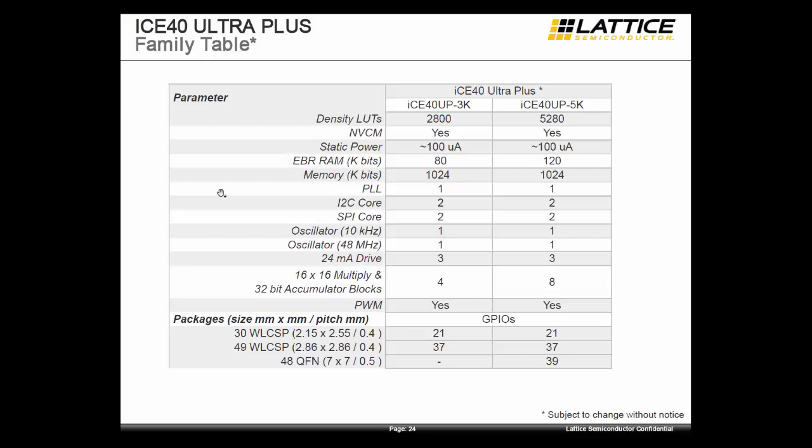The 48 QFN package is a 7 by 7 millimeter package with a pitch of 0.5 millimeters. And the QFN packages do contain all of the pins on the circumference of the device, so much easier to access and probe if needed for troubleshooting.